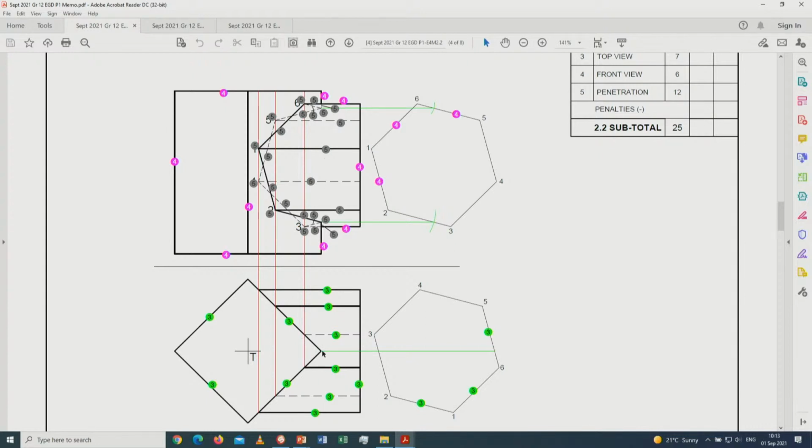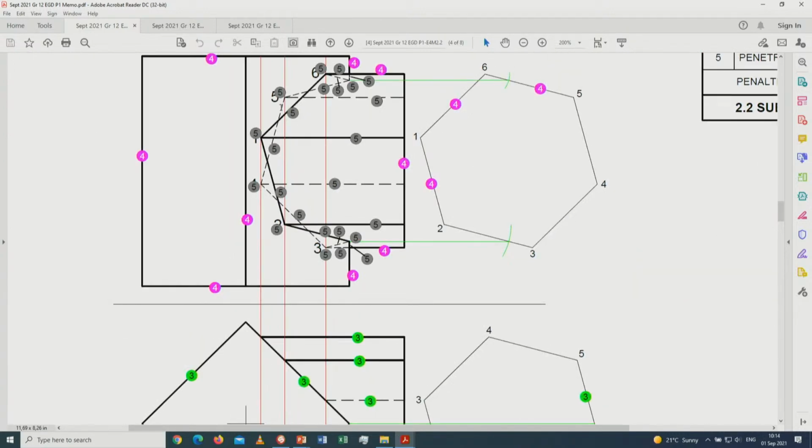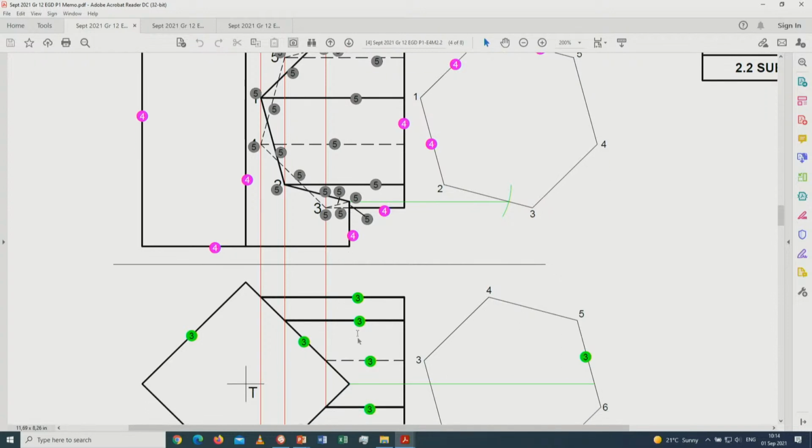All right, so that's what you will see, and then on the top, this is the top line over here, but now it has got a turn point. It goes around this point before it goes to this point, and at the bottom it will go around, oh no, it will go straight from this point towards that point. All right, so that point is basically this line over here that you see. It's the hidden detail line, and it will go straight towards this point. So there's only two turn points at the top between these two points, which is between 5 and 6.